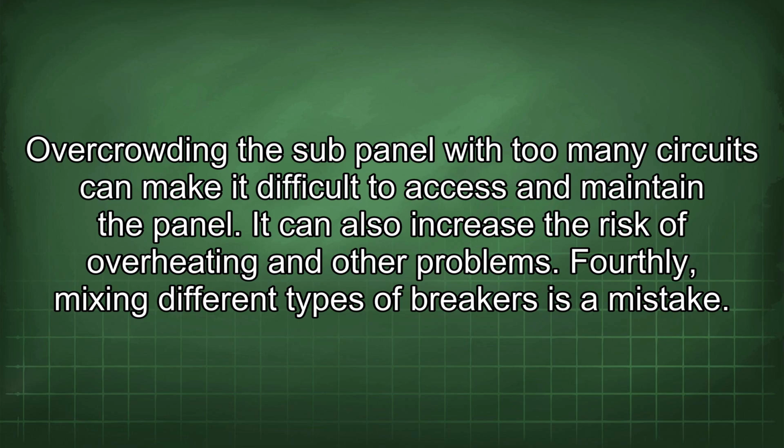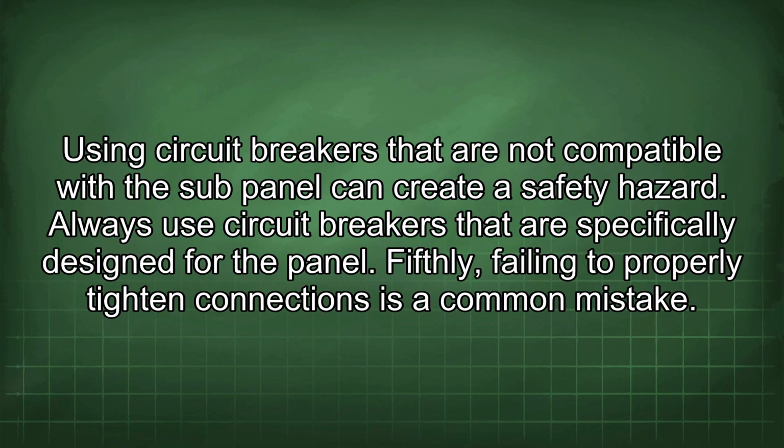Fourthly, mixing different types of breakers is a mistake. Using circuit breakers that are not compatible with the sub-panel can create a safety hazard. Always use circuit breakers that are specifically designed for the panel.